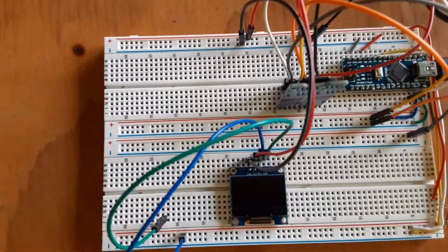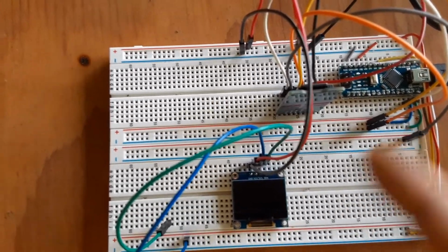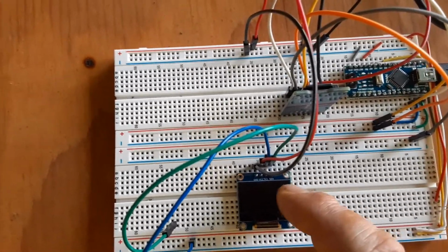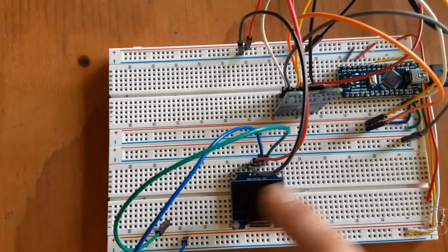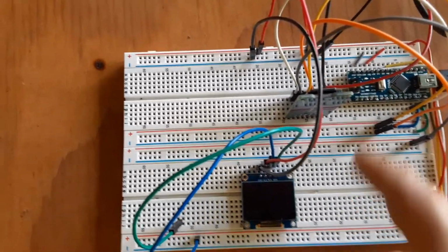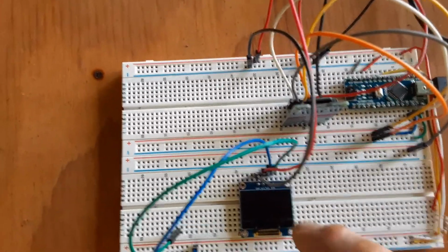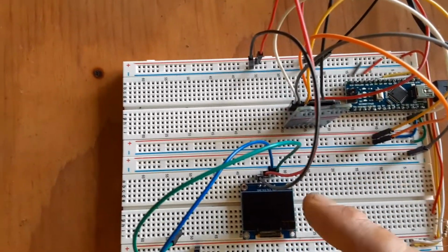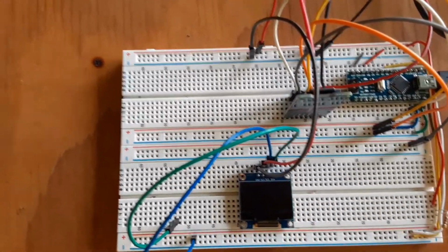So there's some messy spots in the code, so I just used a more basic library for the OLED screen. Very basic, so all it does is spit data onto the OLED. In the case of a text file, it spits the whole text file out as one long line, no line breaks, scrolls to the end, and does that at computer speeds, so near instantaneous as far as we're concerned looking at it. So that wasn't going to work, so I used a more basic library that would allow me to write my own buffers, and I wrote the smallest possible buffer I needed to get the words looking right on the screen here.